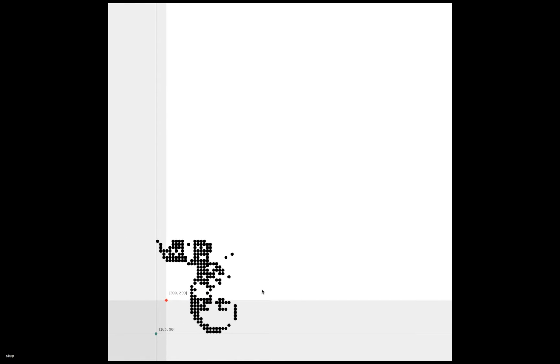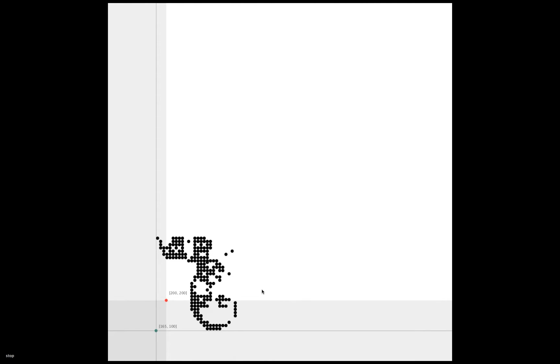So if I clean this up, you can see there's this green dot, which I'm changing with my arrow keys, and there is a gray area, which is like 200 by 200. This is the maximum new origin, where I want my plotter, after getting it homed, to go and set up its new home as 0, 0. I'm not giving the users too much independence to play around with it, because it's the best position which I figured out for that specific drawing plotter machine I'm making, and you can easily take this software and change this according to your needs.